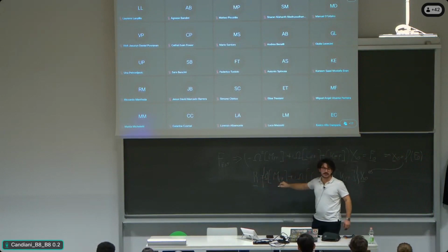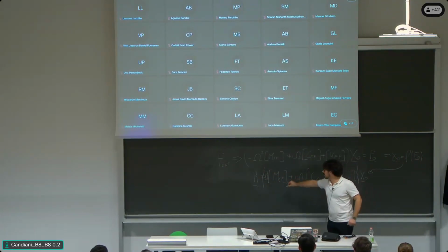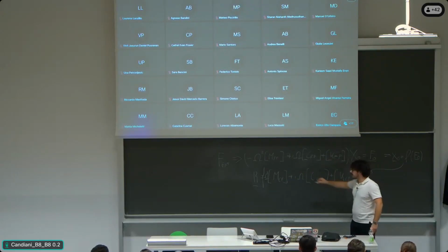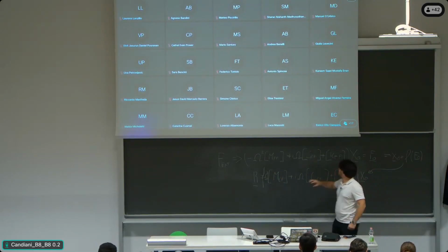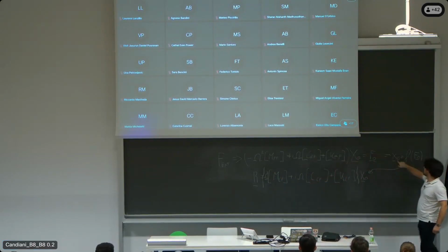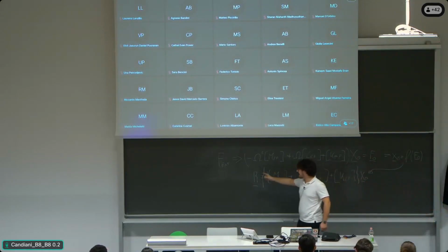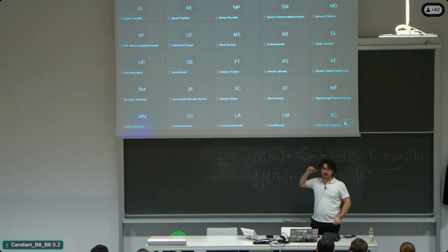Those are rectangular matrices, but in this case, this doesn't matter because we are not trying to solve a problem here. We are just straightforwardly computing the solution. So this is not even a matter of derivation or anything. You just plug in your results and you find the reaction forces. Remember that since this quantity is a complex one, and this quantity again is a complex quantity, also the reaction forces will be a vector, or matrix, of complex values, depending on the frequency at which we make this computation and the input force that we decide to give.